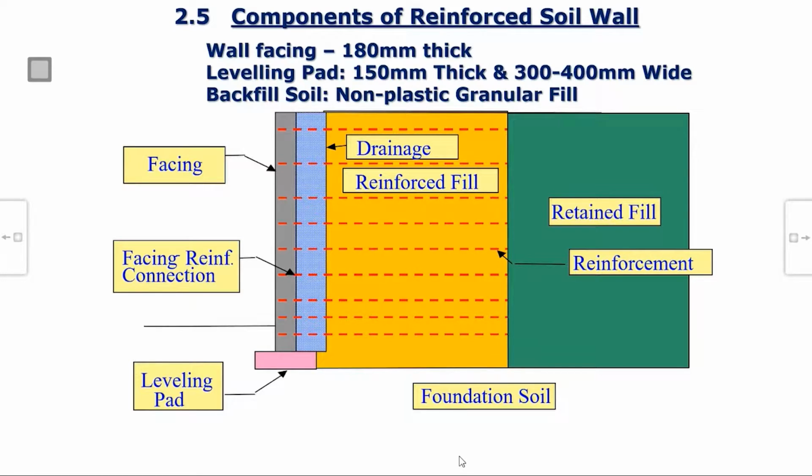In some lectures I heard that this facing reinforcement should not be connected. Should not be connected? No, it has to be. Not in this case. If there is no retained fill, entirely reinforced fill, whether it is true. No. It has to be connected. Otherwise, anchorage action will not be there. When we go to design, I will show you the failure mechanism, you will probably appreciate it. Otherwise, this will not mobilize the required tension.